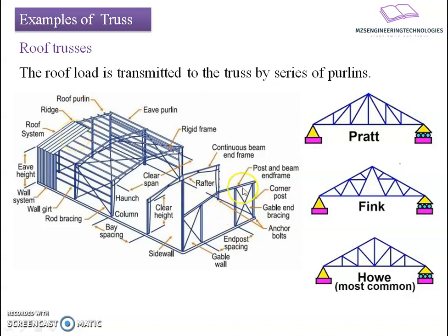Okay, these trusses are connected to each other with the help of horizontal members in the transverse direction, thereby providing distribution of the forces coming from the roof system towards the panel points. The junctions of the truss elements are called panel points, which will receive the loads from the roofing system.